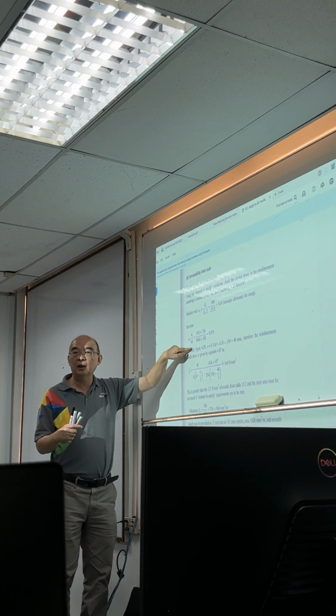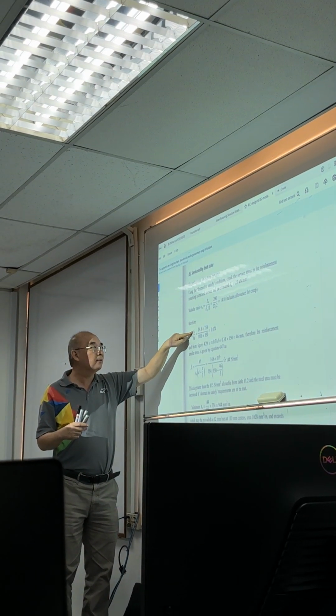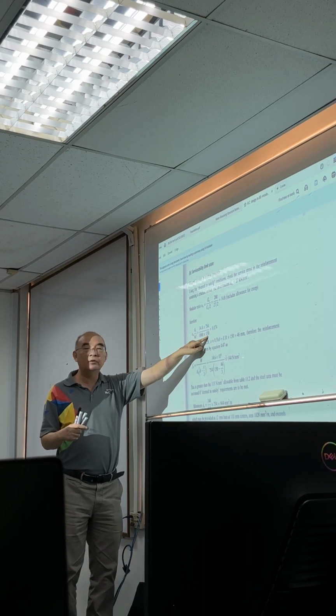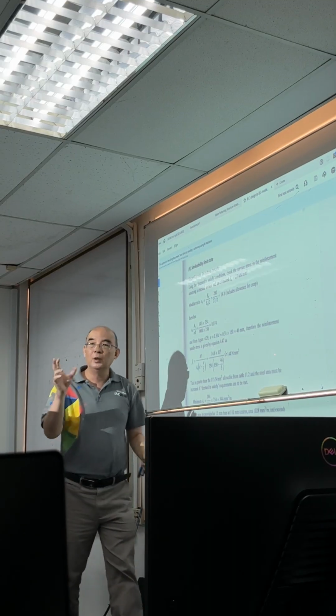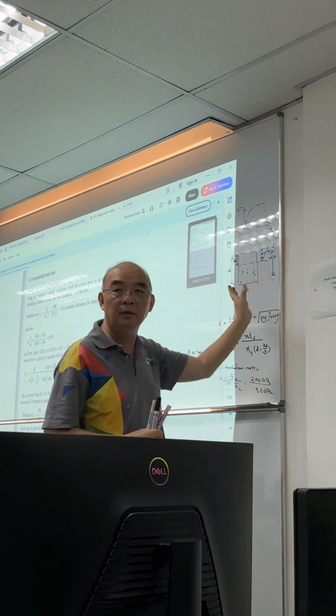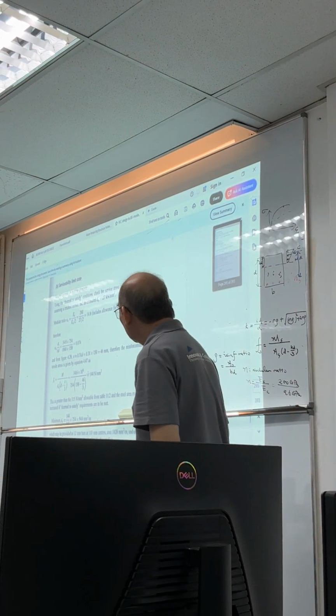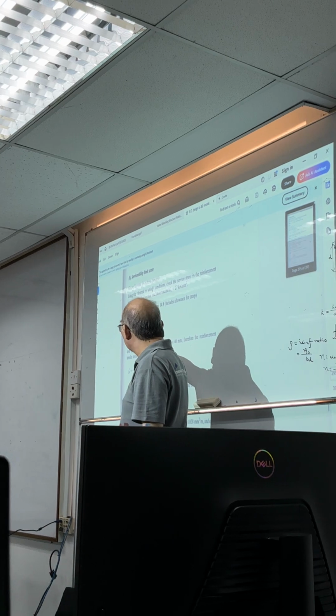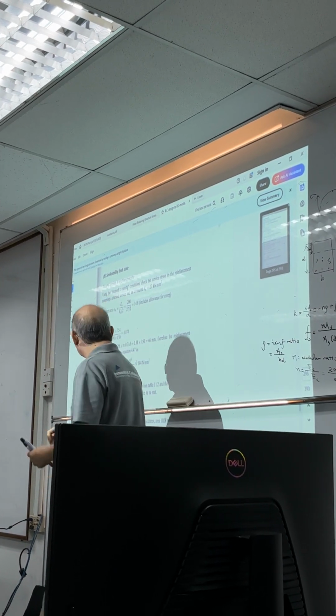Okay, so they try to calculate n rho. Rho is As over B D, where As is 754, D is 150, and B is 1 meter because we are doing it per meter width. So we get this value as 0.074.